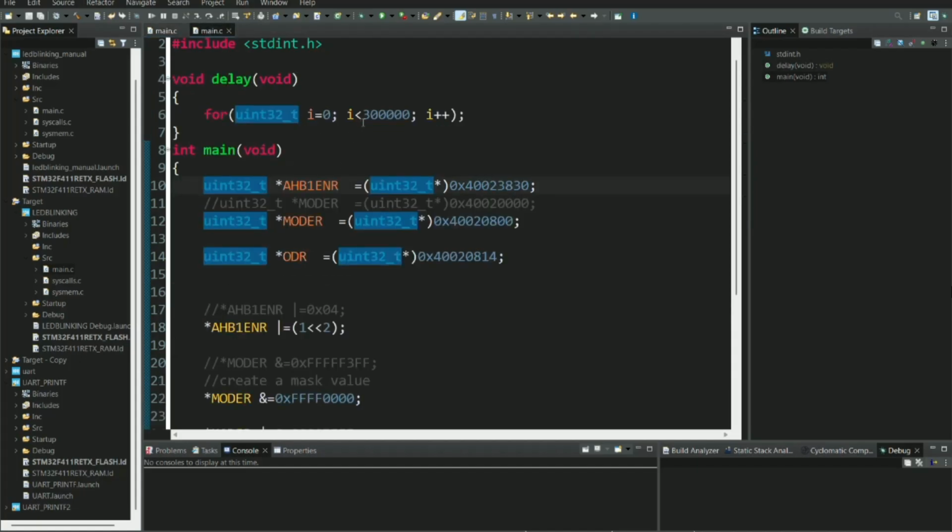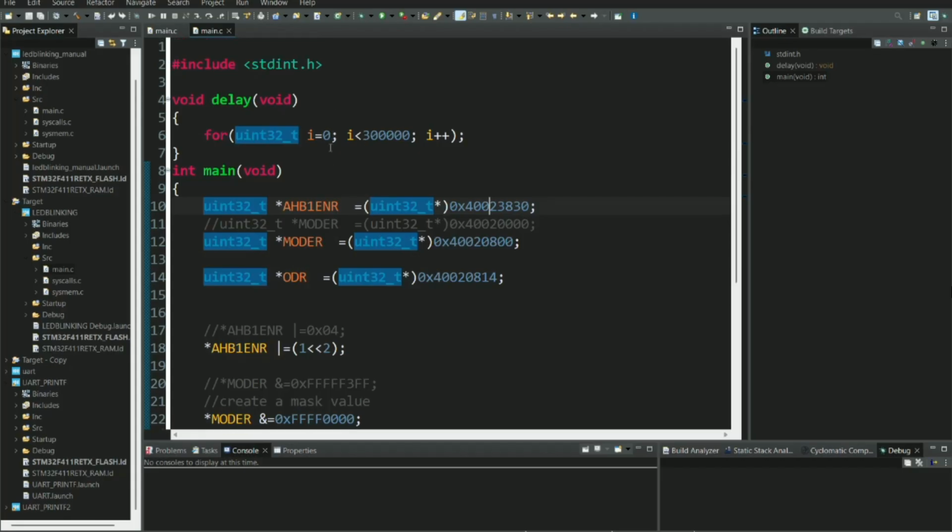And now, how is the external LED connected? Well, the LED is connected to one of the GPIO-C pins, as my partner said, with a current limiting resistor. This pin is set as output, and we toggle its state between high and low. The LED turns on and off. In the code, in contrast to the other, we created a basic delay function using a for loop. It's not precise, but enough to create a visible pause between on and off states.